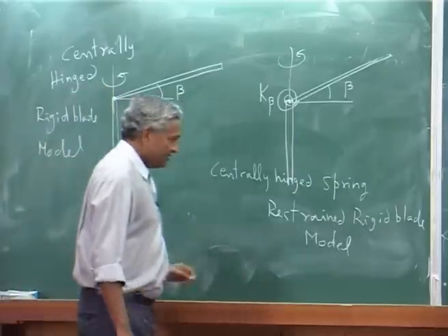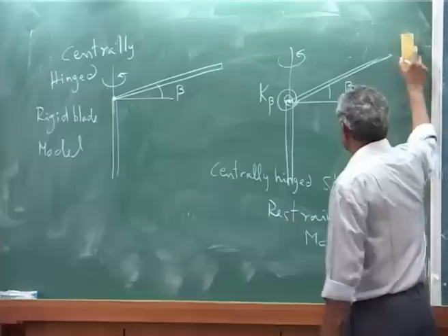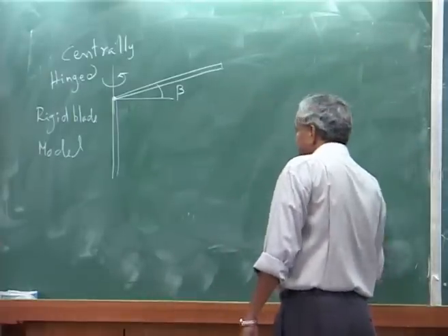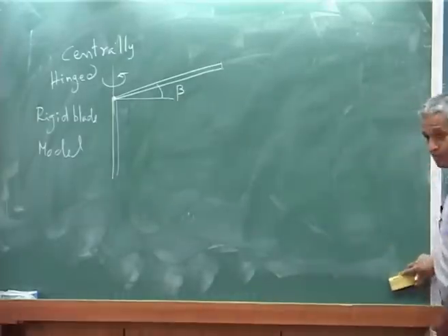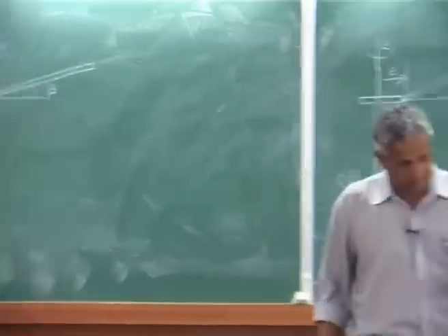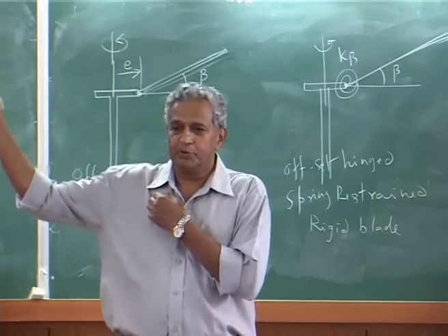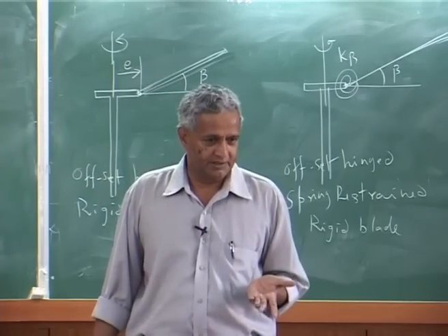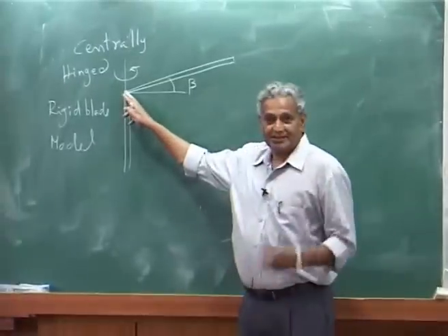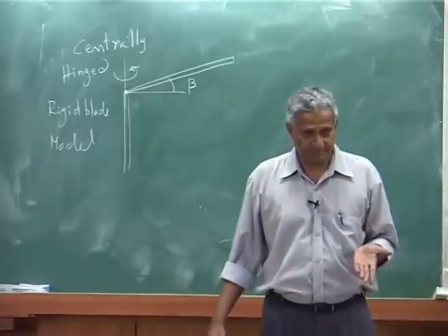Write down the equation of motion. So how do we write the equation of motion for this? We have the basic dynamics, and of course aerodynamics is there. You have to combine both. The external loading is aerodynamic, and because it is moving, you have an inertia. And there is no restraint here, so the moments must balance.